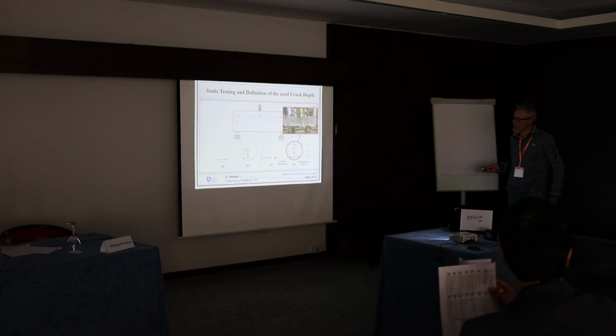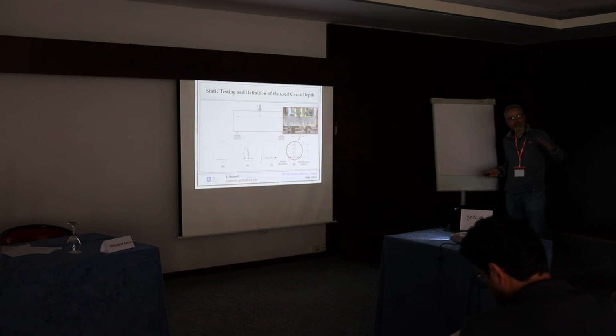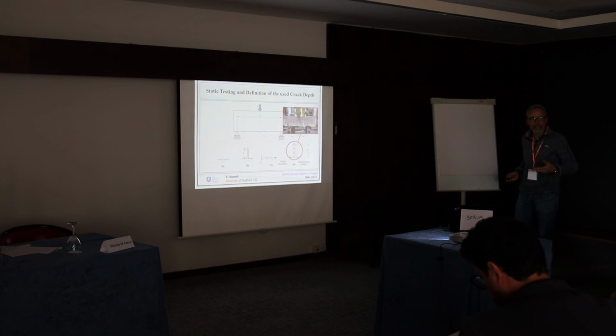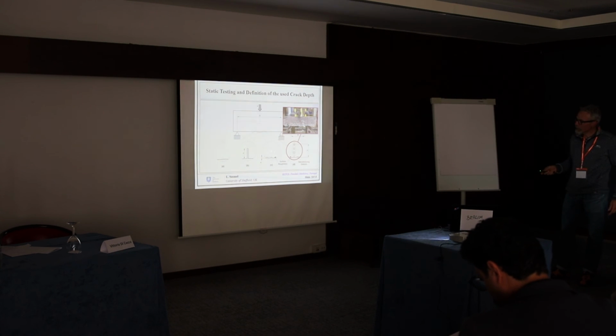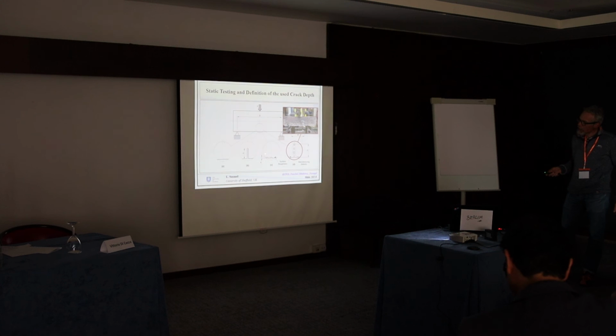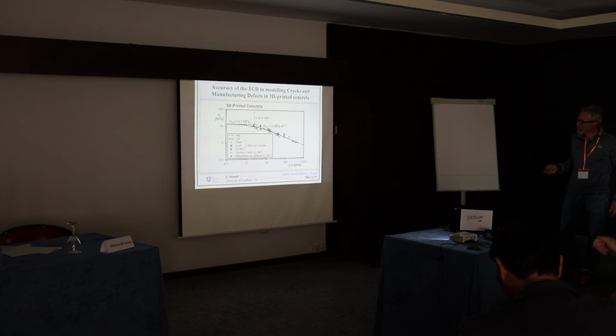The surface roughness is the average peak and valley. You measure roughness of real components and scale it up, because you don't need an accurate tool to measure it. But this roughness, the conventional one you get, for instance, we were extruding sausages of concrete having a diameter of 6 millimeters. In a log-log schematization, compared to the plain material behavior, you have a reduction which can be up to 20–30% in terms of strength. So it plays a very important role.